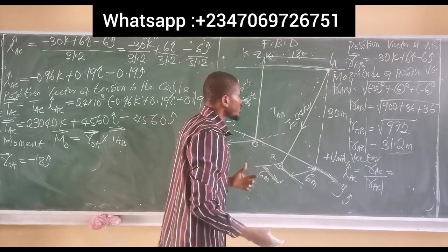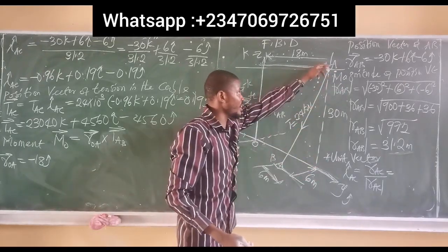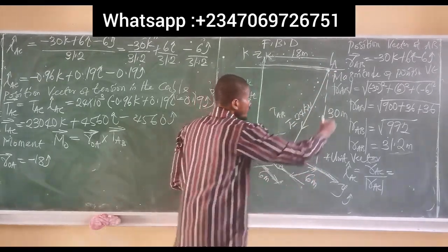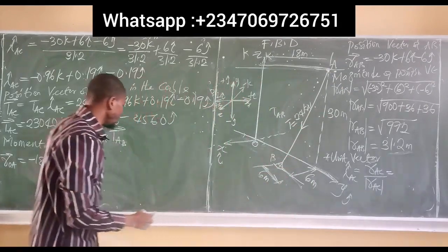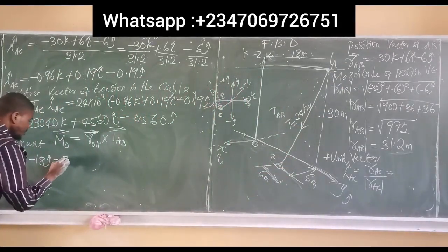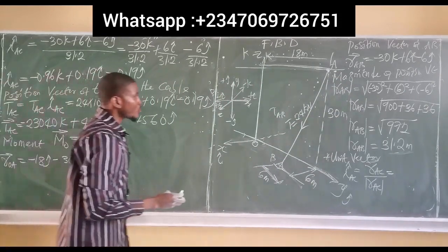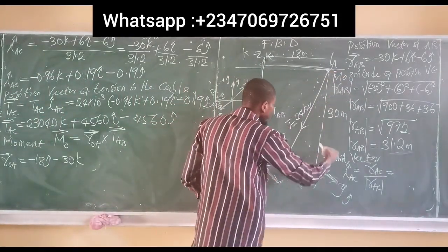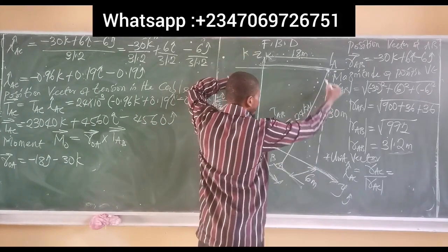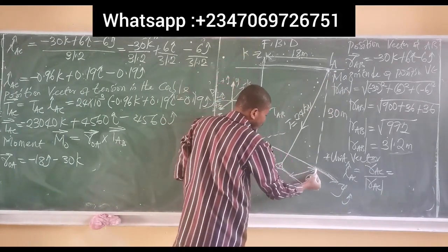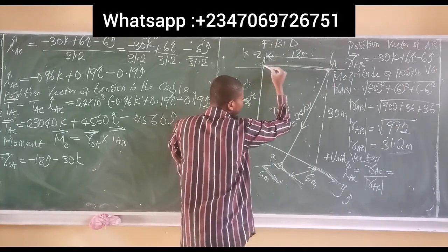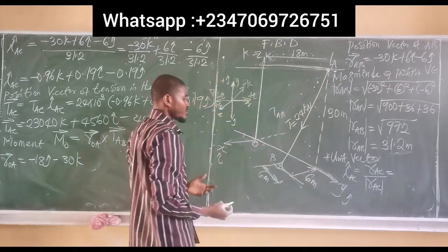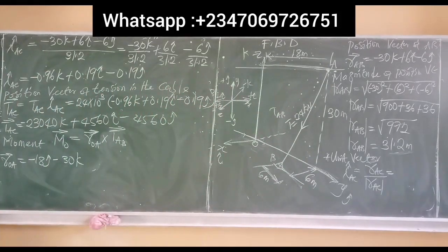You can still move from here, which is point A, to locate point O. You've covered this distance acting downward, which is minus 30 in the k direction. Since you're going against z now, it becomes negative because you're moving downwards. Either way it's the same distance, so it's virtually the same thing. So we have the position as minus 18j minus 30k.